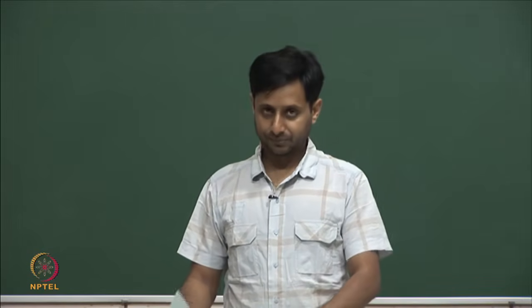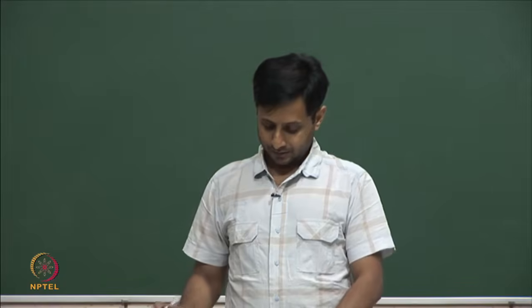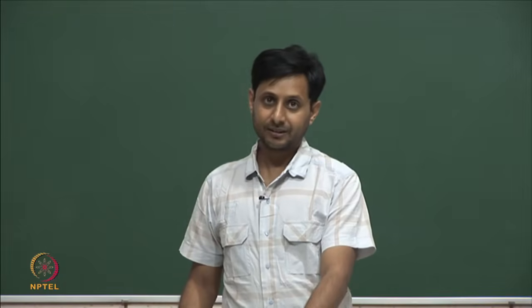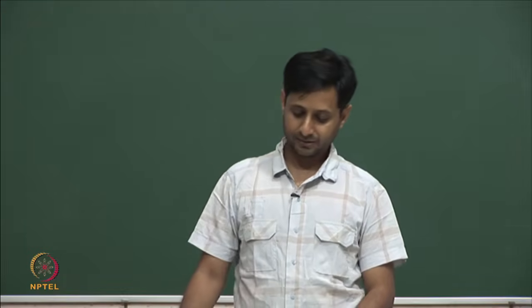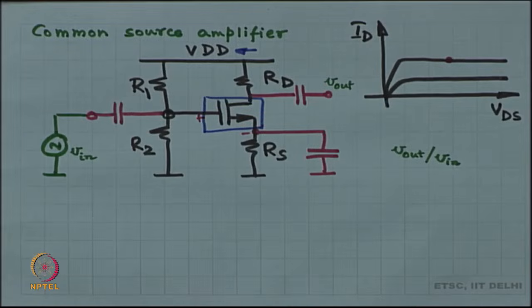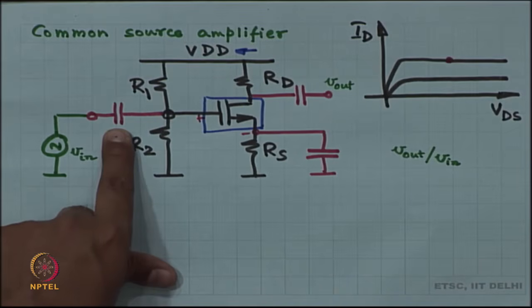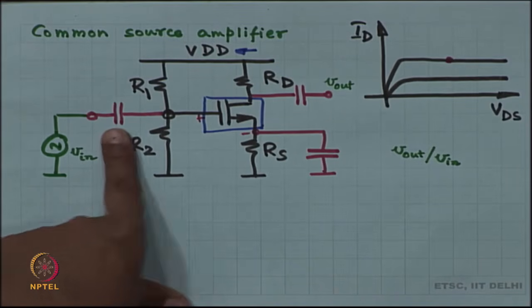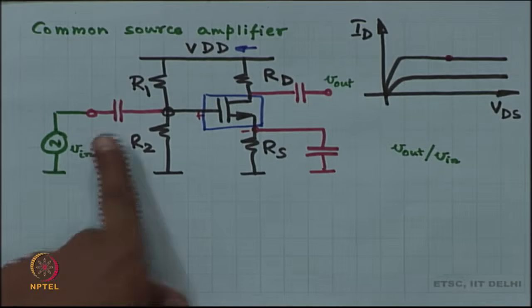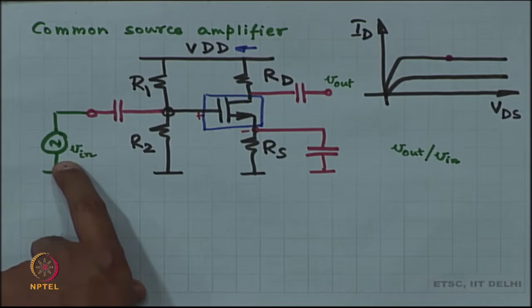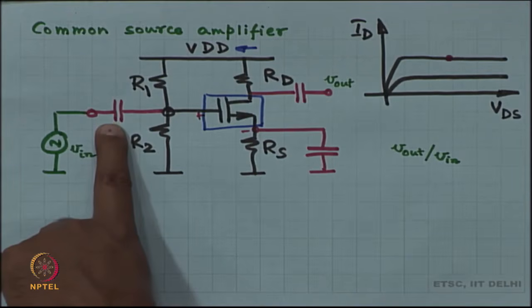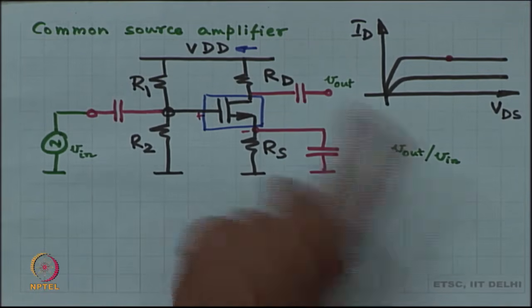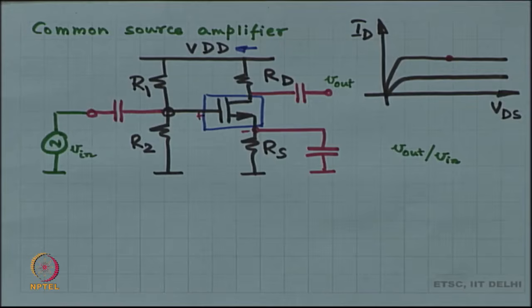So, let us do this. The resistors, capacitors, what is going to happen to the capacitors? Yeah, the resistors remain as is. The capacitor was chosen to be so big and fat that when a signal is changing with time, this capacitor is going to behave like a short circuit. So is this and so is this, right. They are all going to start behaving like short circuits.